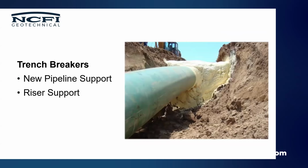Trench breakers. We mentioned this at the beginning of the presentation. Trench breakers are used in the oil and gas industry for the installation of pipelines. Ironically, the sandbags that we just talked about used to be used for this type of application, but with OSHA regulations trying to keep humans out of the trenches as much as possible, it's very labor intensive. Yes, sandbags are going to be a cheaper product, but there's a lot more manpower involved and a lot more risk of injury. 50-pound sandbags being tossed down into a trench.